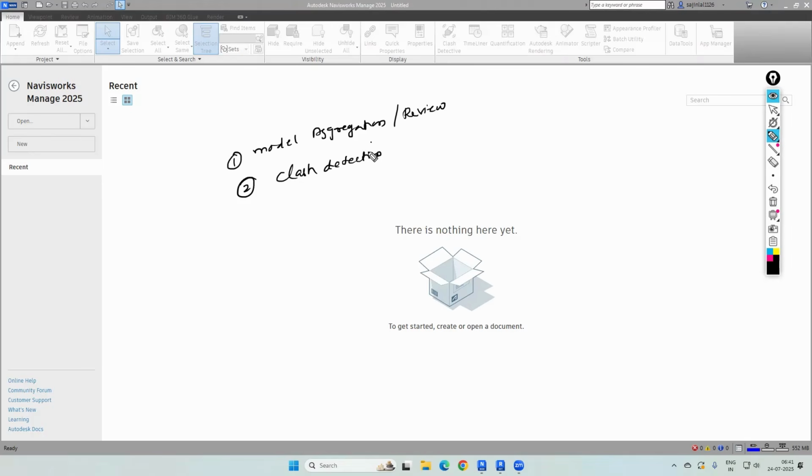Anyhow, the changes that we do after uploading any models within Navisworks will not affect reality. Just for switchback or witnessing purposes, we can use that. But really, those changes will not affect Revit. Even though we can generate the clash detection report with the help of Navisworks, the real clash correction, everything, we have to do in the 3D software itself. Means if it is a Revit file, in Revit itself. Anyhow, we will study that in the upcoming classes.